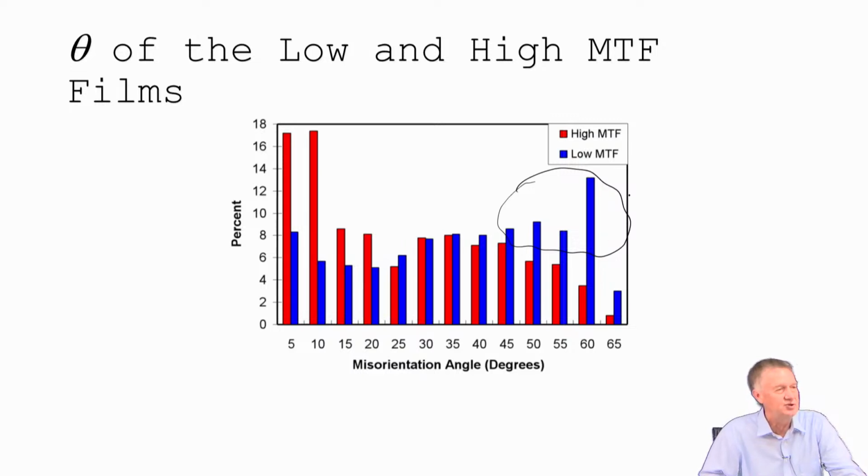It's a lot easier to describe it that way than trying to say, well, I wonder if 111, the low surface energy, has lower diffusivity because it's a low energy surface than a 200 surface, for example. And so maybe it's surface diffusivity that causes that issue. But in this case, it's all the boundaries. And so it's not really the texture from that equation that we showed that's governing the behavior. It's actually the grain boundary character that governs that behavior.